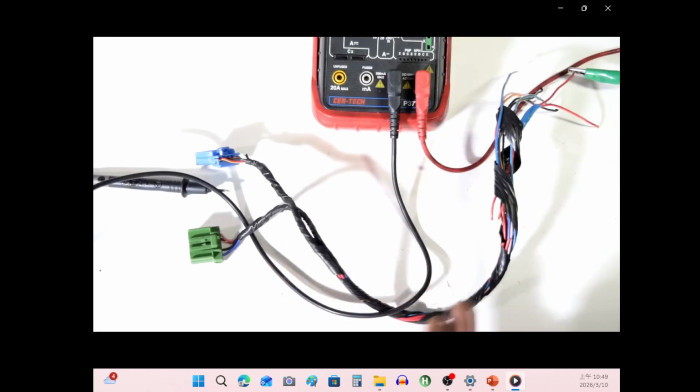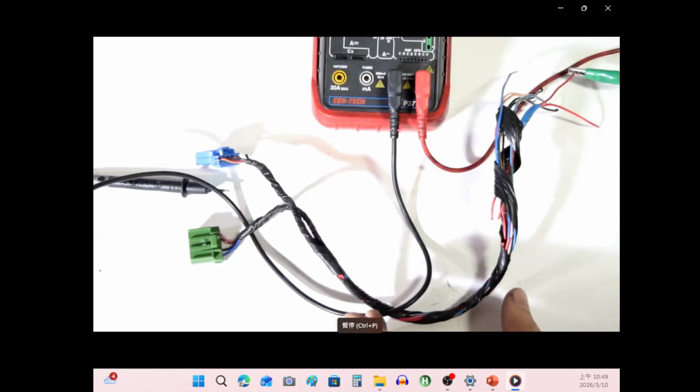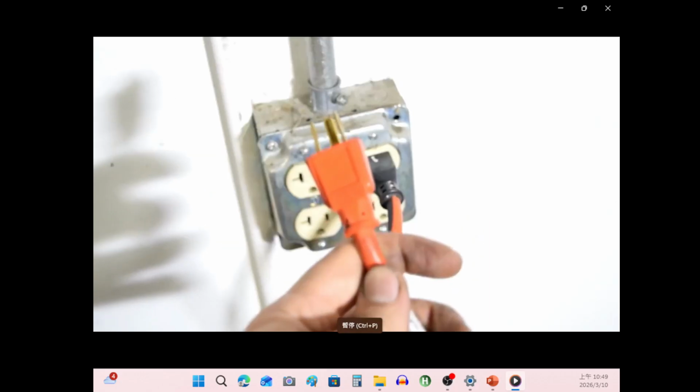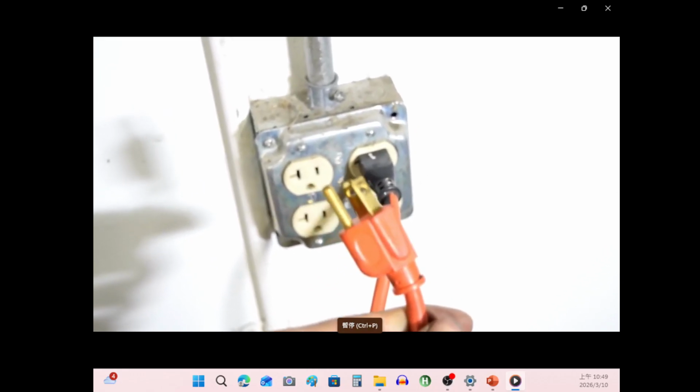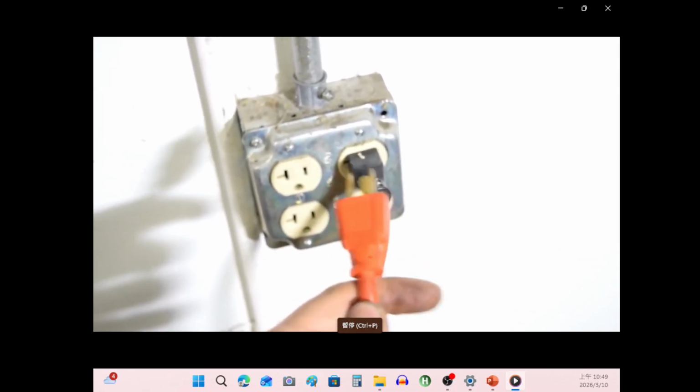I did this test on a rather small scale, but this can be done on a much larger scale, or in other words, larger circuits, or even smaller circuits than this, like a motherboard of your computer. A word of caution though, whenever you test for resistance or continuity, you have to make sure that the device is not powered, so either unplug it or remove the batteries.